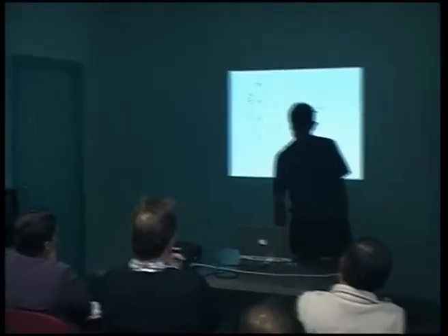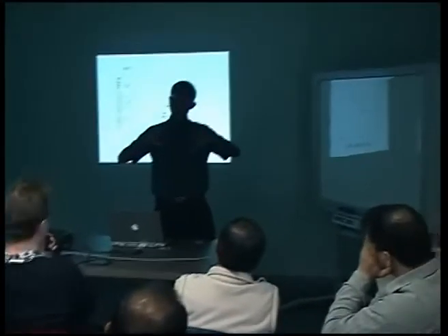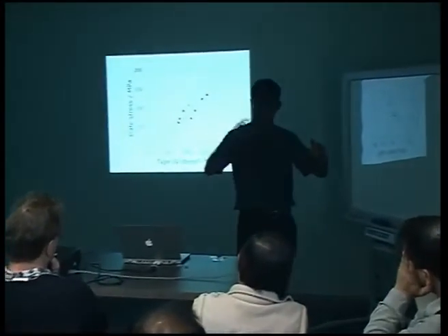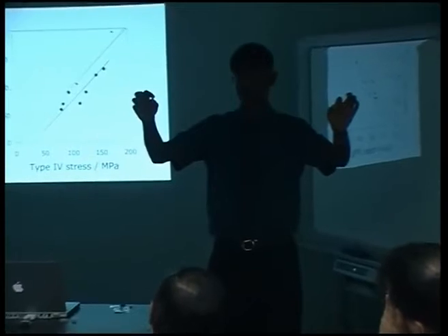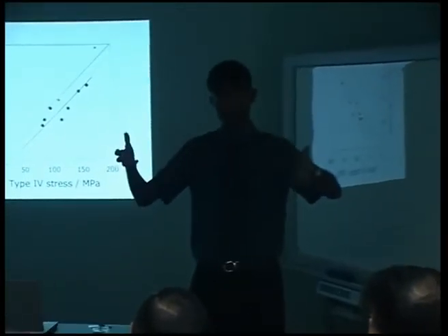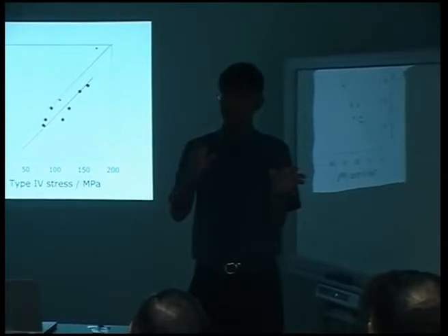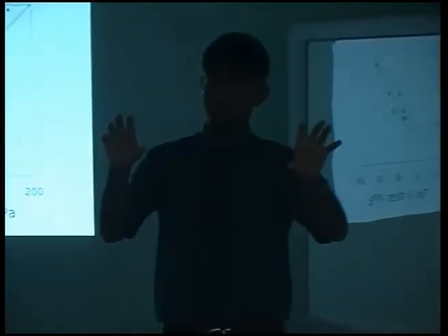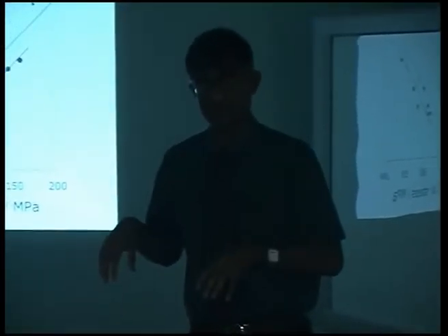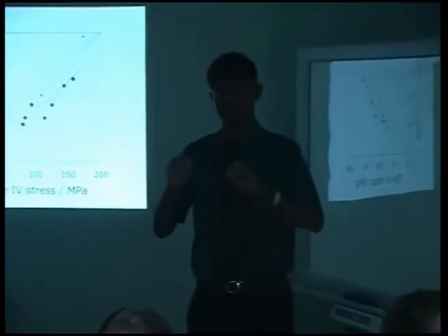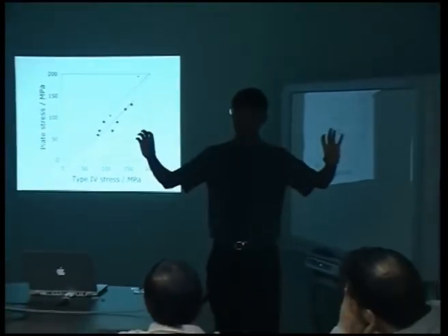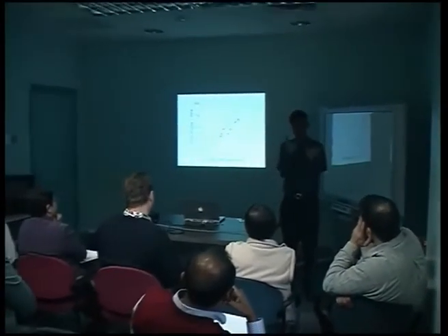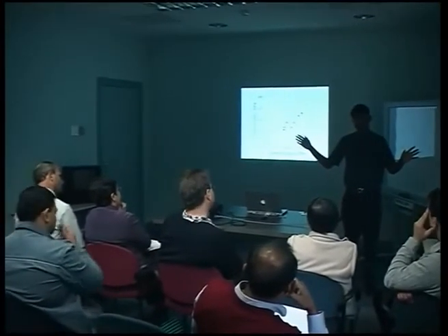Toughness hasn't been done, but the creep rupture strength, I showed you, that M23C6 is contributing so much and so on. So what we've done is we've taken thermodynamics. For each steel, we calculate the fractions of phases and the compositions of phases, so that we can put solid solution strengthening terms and so forth. And we use those as inputs to model everything else. So instead of using, say, the raw chemical composition and the heat treatment as inputs, we use the microstructure as inputs to create the model.